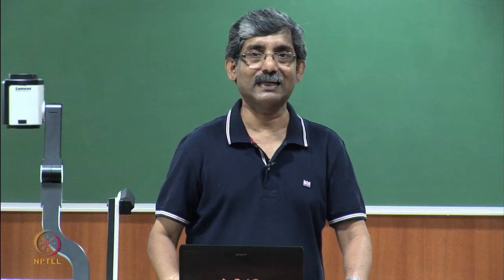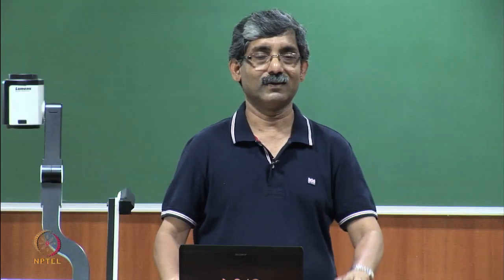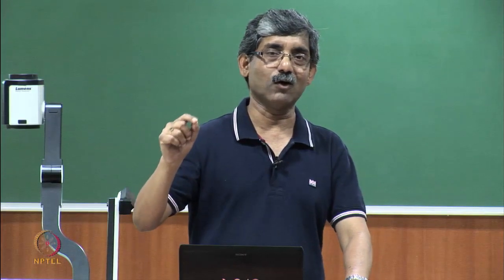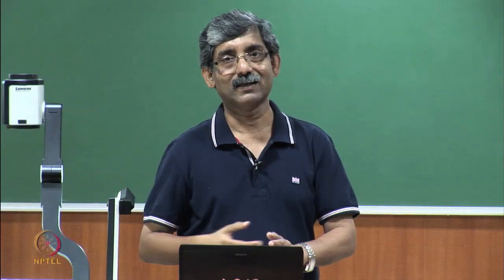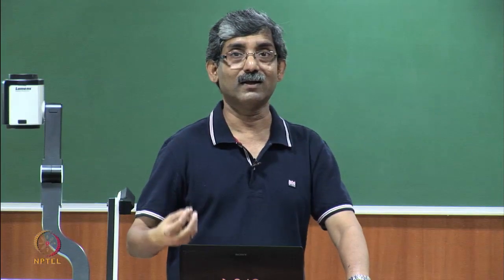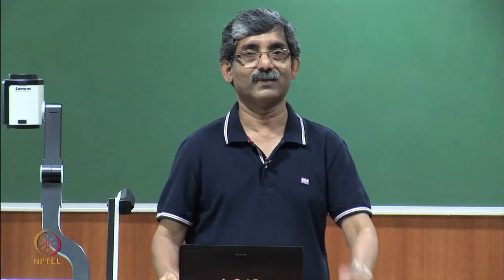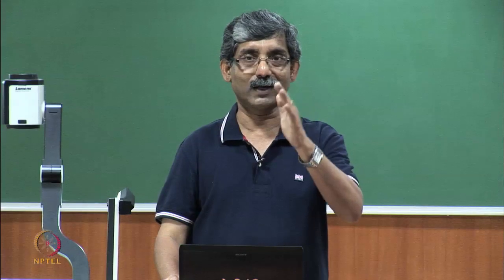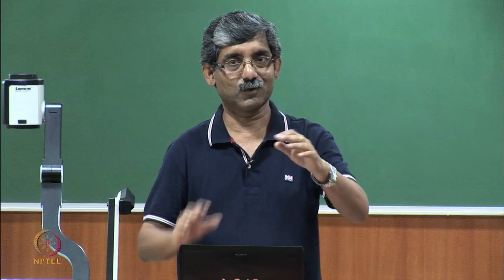So, say at tension T, the number of breakages occurred is say 10. The standard is that, say, 20 breaks per 1000 yard, and the tension required to have 20 breaks is the value we want. If we get less than that, then we increase the tension, till we get 20 breaks per 1000 yard.